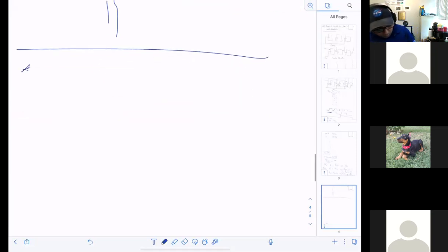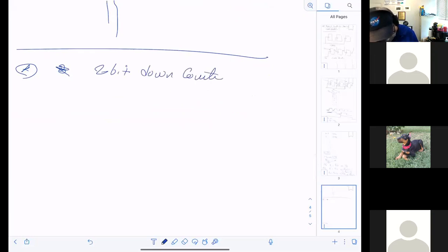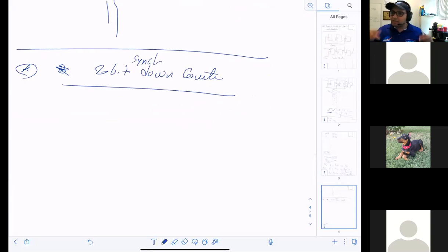Anyway, now, what if I would like to do a down counter? I'm still going to use the same trick. Do you guys agree? Let's make it easy and imagine that I would like to implement a 2-bit synchronized down counter. And this counter, once you connect the clock, it will be working. That means we don't have a control enable or anything like that, right?